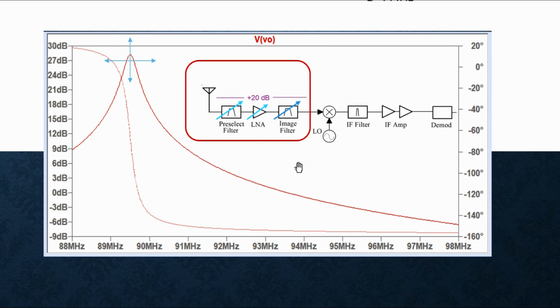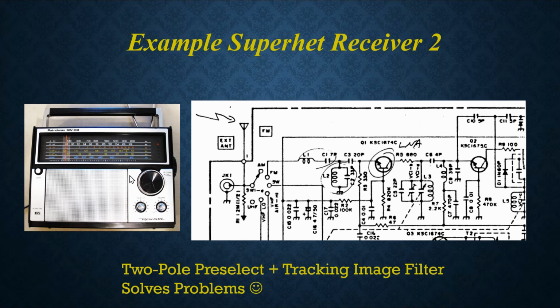And part of the reason is captured in this block diagram. The old radio has this knob here that tunes some capacitors inside, and you can see one of them right here. This is its low noise amplifier. It's just a simple common base design like we've been talking about in our prior episodes.